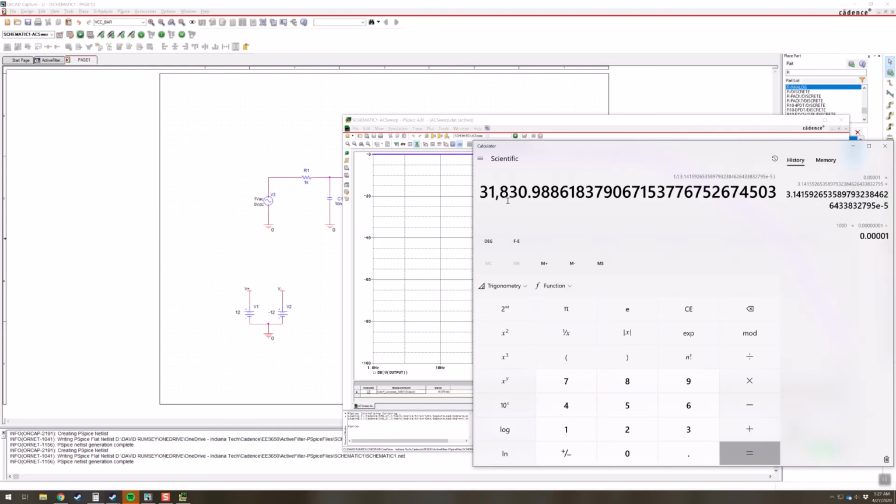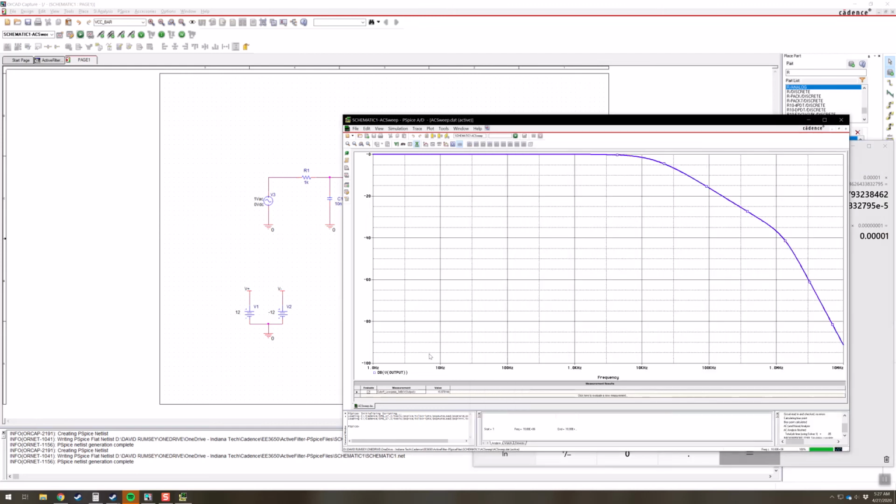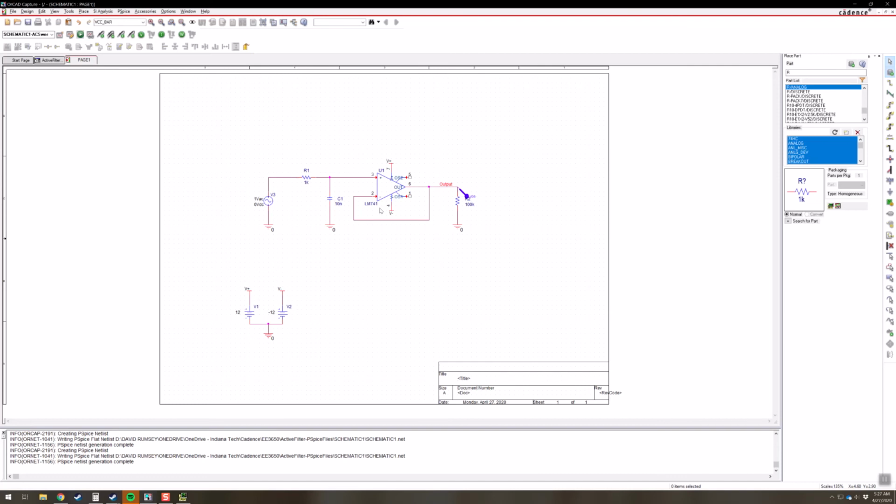And you might say, well, what's going on here? Is there something wrong? No, there's nothing going wrong with our equations here. A lot of it has to do with the op amp itself, and that the computations make some assumptions here. Again, some of the assumptions we're making is that this is infinite impedance, which is okay for that, but also that the current going into the things is 0. So there are assumptions being made.